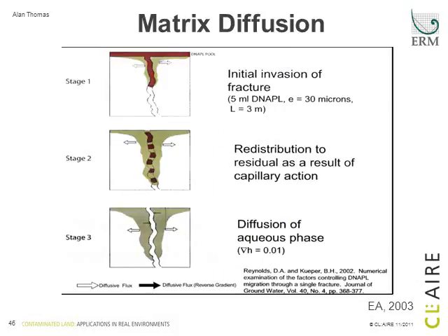And just re-emphasising this importance of matrix diffusion. Many of our major aquifers are dual porosity aquifers, things like the chalk, and in those environments there may well be this phenomenon of diffusion of contaminants into the matrix, such that when we undertake remediation of the fracture zone, there is long-term back diffusion that may well impact on the overall success of the remediation. And it's about acknowledging this and building this into your remedial design to the extent that you can.